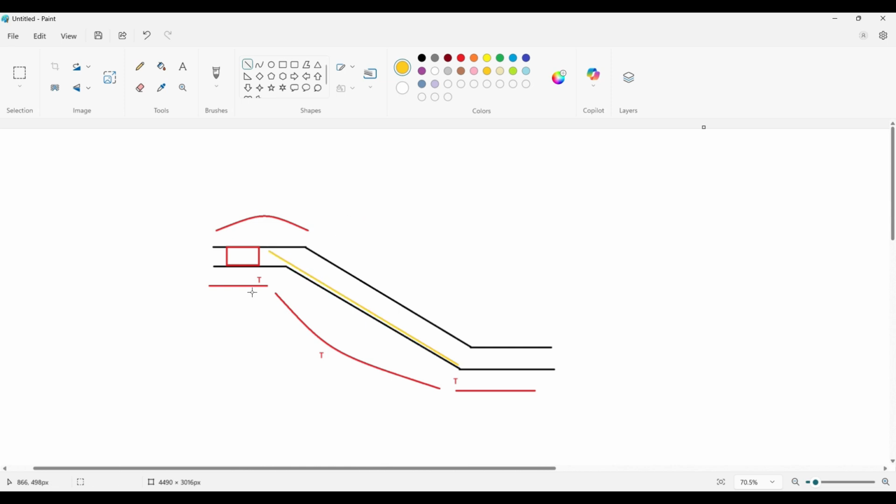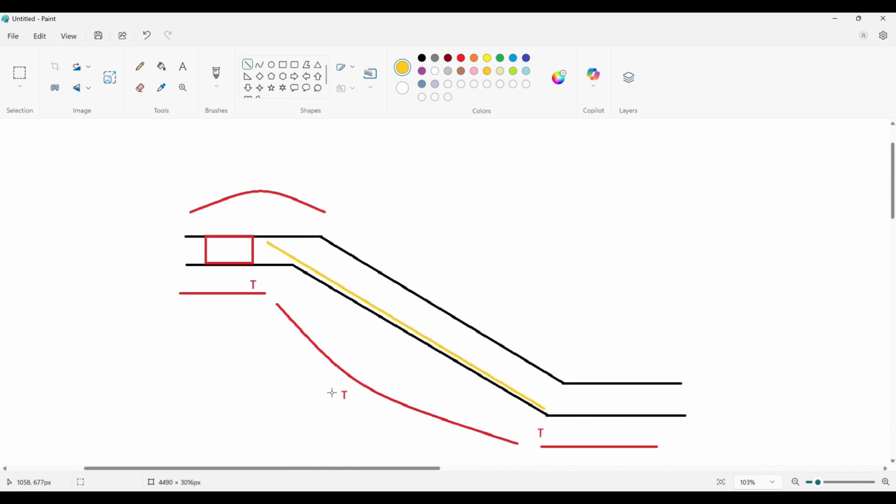Okay, this is very important. Just zoom in a bit more. So tension is there at the bottom, so I'm providing the bottom reinforcement as my main bar, and because tension is there at the top, the bottom rebar which was there, the main reinforcement, is going to go and get converted here like this.